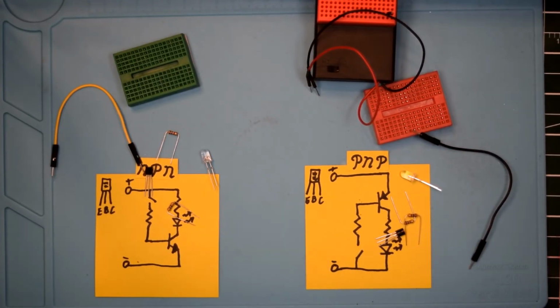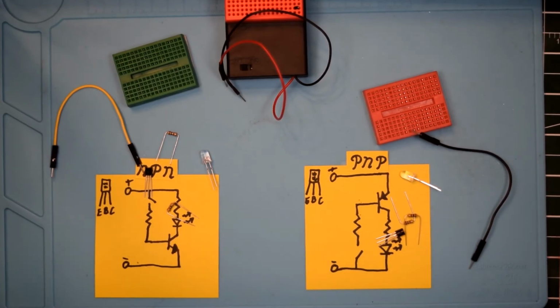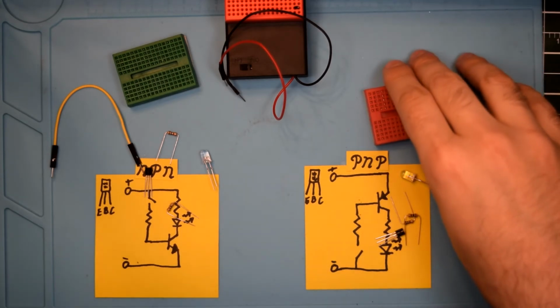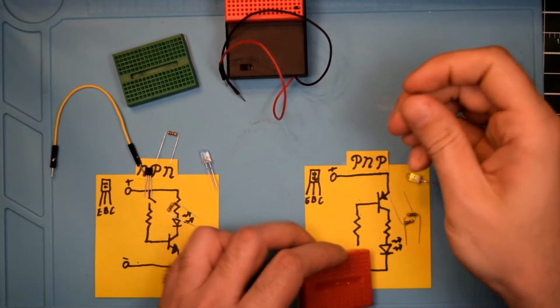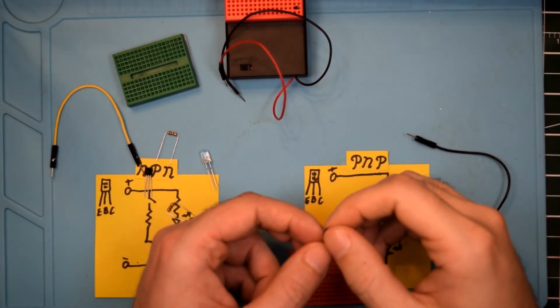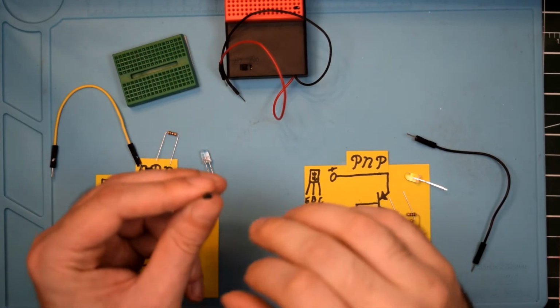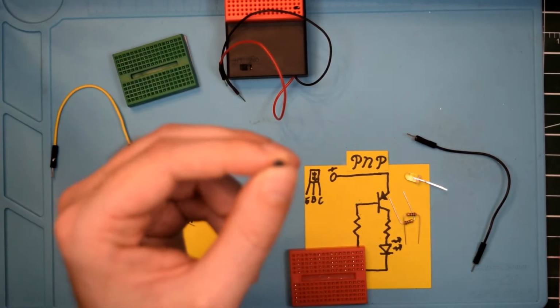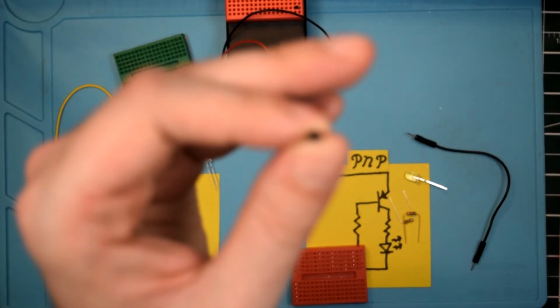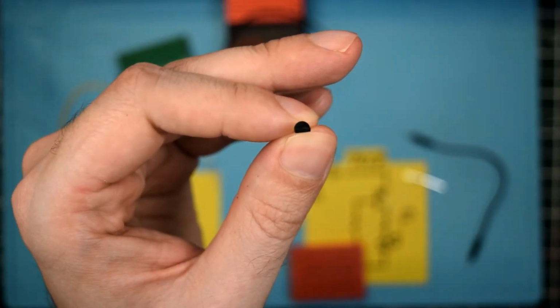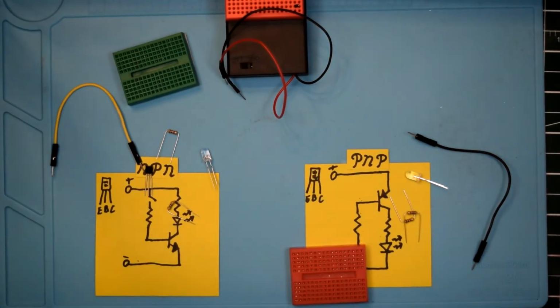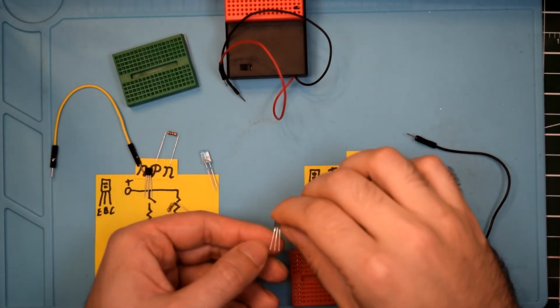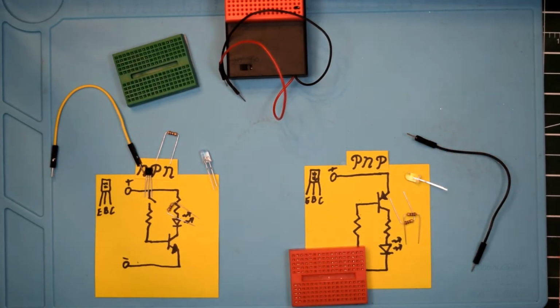Alright, and we're back. I have some breadboards here and some components, and I decided we'd actually go ahead and build them on camera as well. So let's start with the PNP circuit. Now, with transistors, you'll find that there is a flat side on them. I'm not too sure how well it's going to show, but let's bring it up. See how it's sort of semicircular there, and there's some writing on the front? Well, when you're looking at the writing, the pinout is emitter base collector.